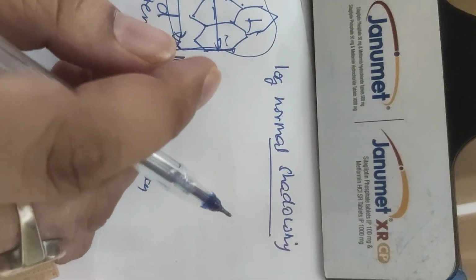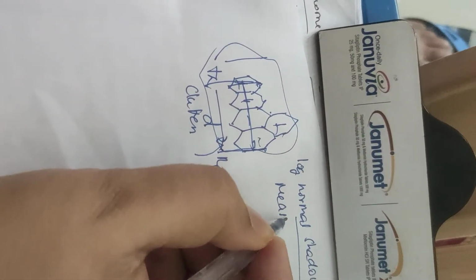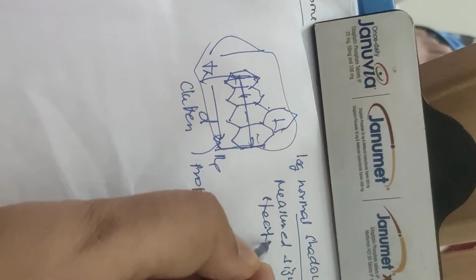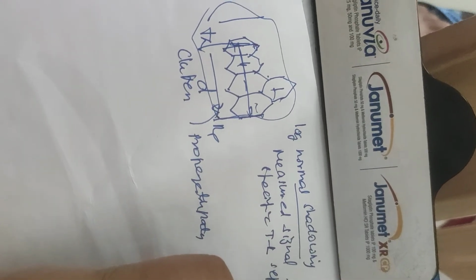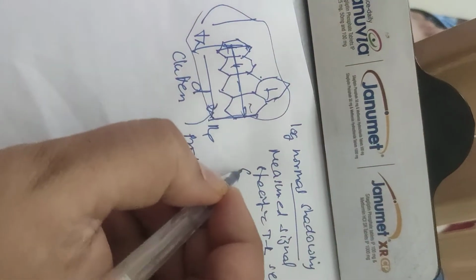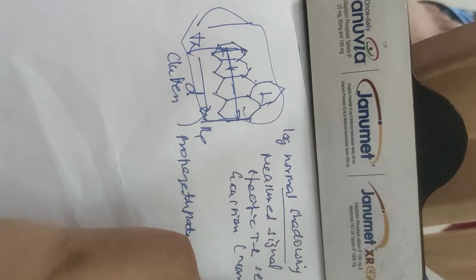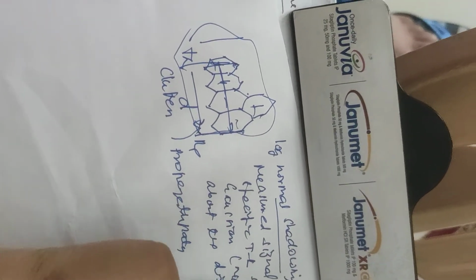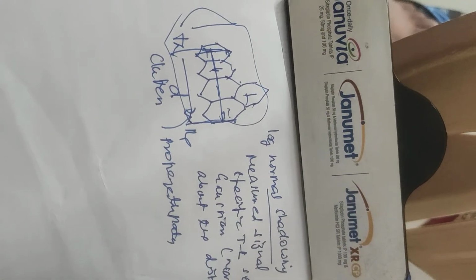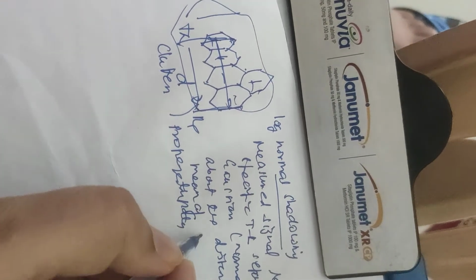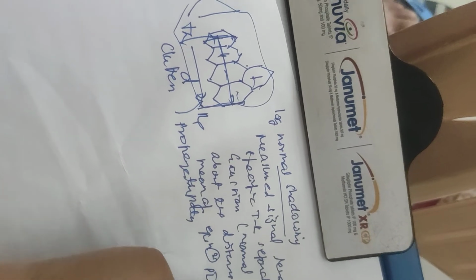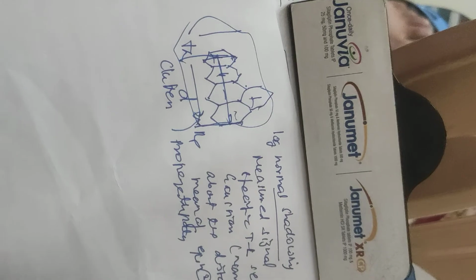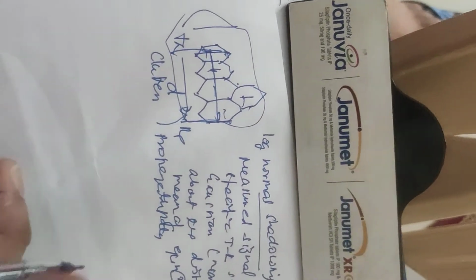Simply, log normal shadowing implies that the measured signal level at a specific T-R separation distance has a Gaussian normal distribution about the distance dependent mean, by means of equation number 2, that is PL(dB) = PL(d0) + 10 n log(d/d0) + X sigma, where the measured signal level has values in dB units.